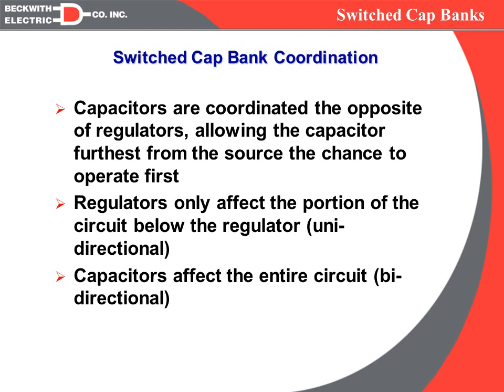So, with that in mind, we need to quickly talk about switched capacitor banks and how we're going to coordinate them. Now, we said with regulators, we want the regulator closest to the source to be the first to operate. With capacitor banks, it's exactly the opposite. We want the capacitor bank furthest from the source to be the first to operate.